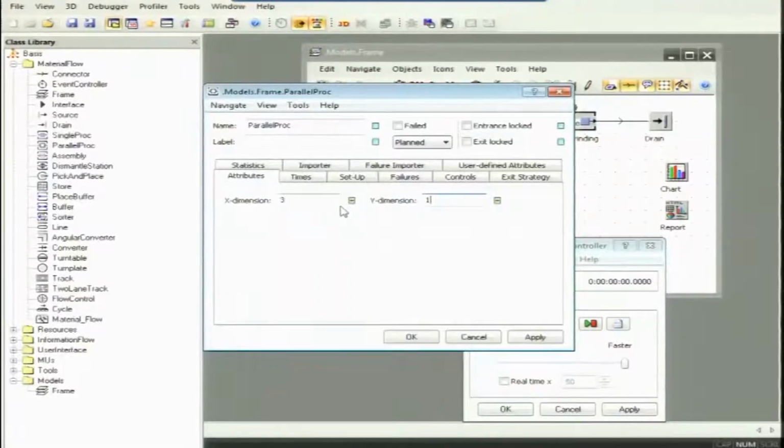When there is waiting or blocking, we can think of adding new machines, or taking a few machines off. If there is a lot of waiting time, we can even think of doing some other processes, like I said in the case of the process layout. In a process layout, we have a specific set of machines in one section and another set in another section. If we see that for 30% of the time there is a waiting in a specific section, we can give them some other job.